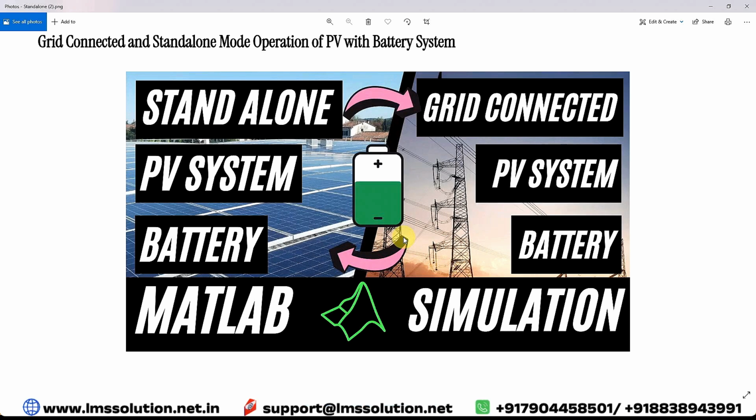Whenever there is no grid power or the grid is disconnected from the system, then the PV system and the battery should be operated as standalone in order to supply AC load as well as DC load. Whenever the grid is available, it is going to be connected to the PV system and the battery. Based upon PV system parameters, that means PV current or power or battery SOC, we are going to decide whether we send the power to the grid or get the power from the grid to supply the AC load as well as DC load.